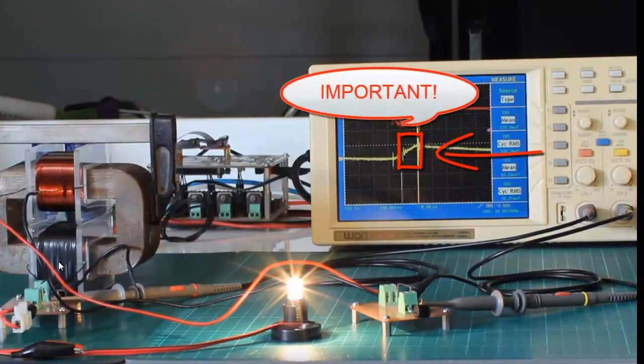So we do want an input coil that is going to be able to have that jolt. Remember, we talked about in the past, we found that it's the change of current that creates a voltage. You can push as much current through the wire as you like, but if it's not changing, then it won't produce any more voltage. So we switch our voltage on across the coil over here, and bang, the voltage is on.